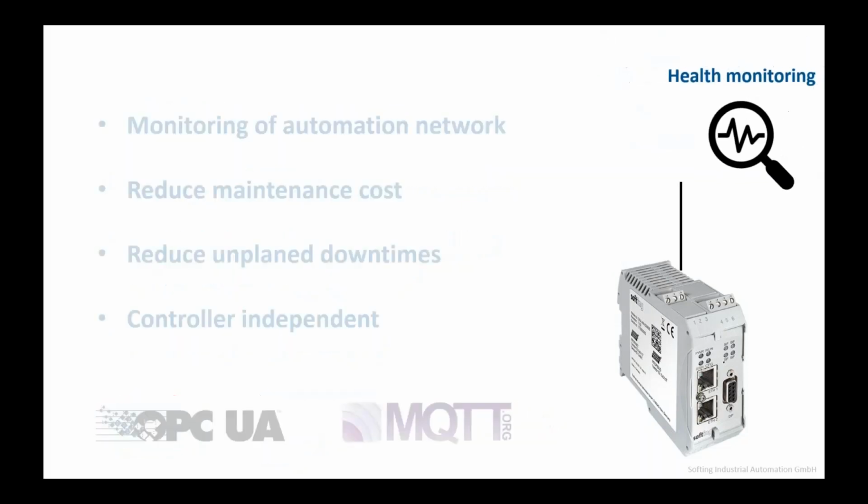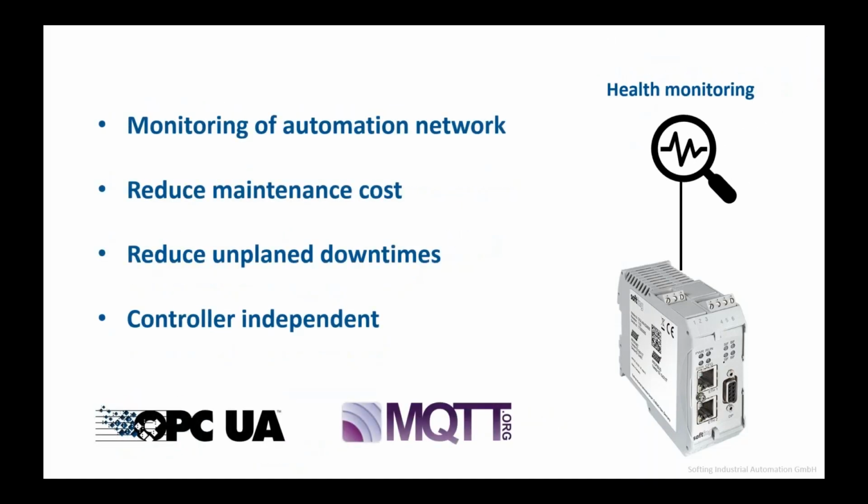And what we lastly offer is health monitoring, as described already. Health monitoring, a big thing. Not health monitoring of the process itself, but health monitoring of the system, of the assets. Like, is everything in the automation network itself going down right? Are packets transmitted well? Are the assets still up? The remote IOs, every single card, every single module. Do we have a wire break or something like that?